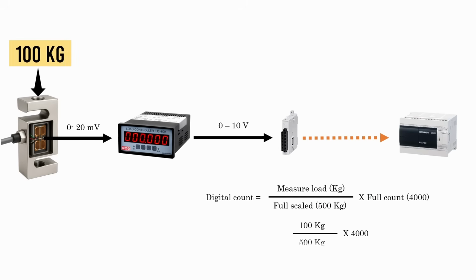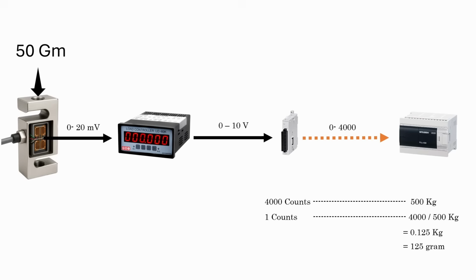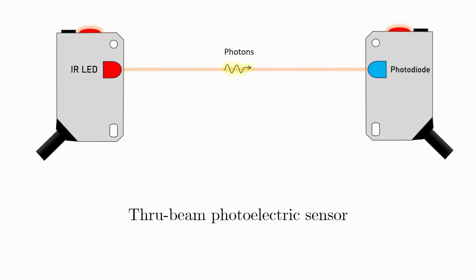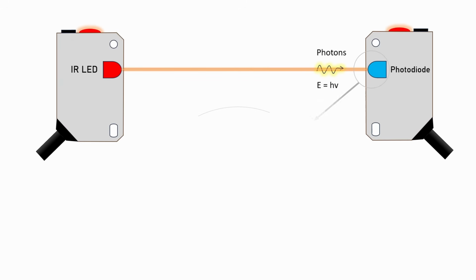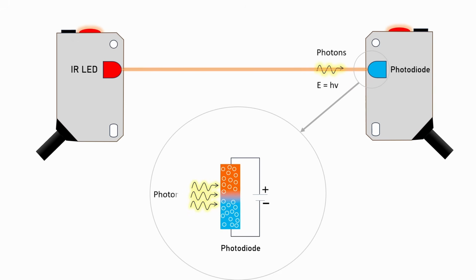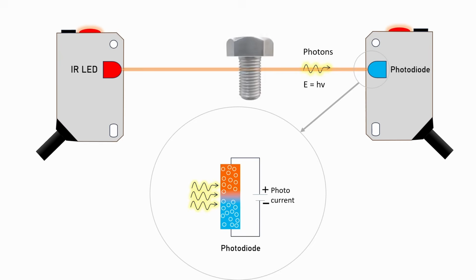We often stop here. We think it's an electrical engineering part, a programming part. But for us, it's important to know at least the basics, because this understanding defines the sensor accuracy, errors, and least count that we get in the final result. And the same thing happens with digital sensors. We understand how a photoelectric sensor detects an object when a light beam between transmitter and receiver is interrupted.